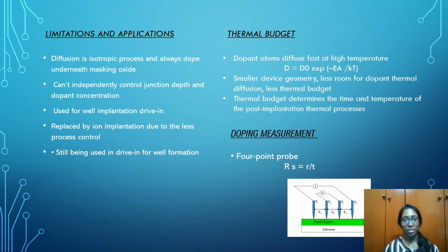Moving on, thermal budget. Thermal budget determines the time and temperature of the post-implantation thermal processes. The equation that I've inserted simplifies the situation where the dopant atoms diffuse fast at high temperatures. The factor is that smaller device geometry leaves less room for dopant thermal diffusion, which contributes to a lesser thermal budget.